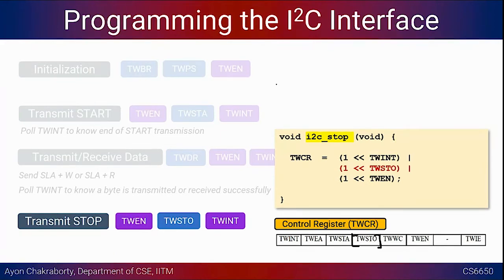Any sort of sensor you buy these days will, in most cases, have an I2C interface, and they might even additionally have an SPI bus. And sometimes they might have just the SPI bus. It depends on what kind of data rate that particular device is going to give you. Normally, an I2C device does not give you a very high data rate. It could be at most 1 or a couple of megabits per second, not more than that.